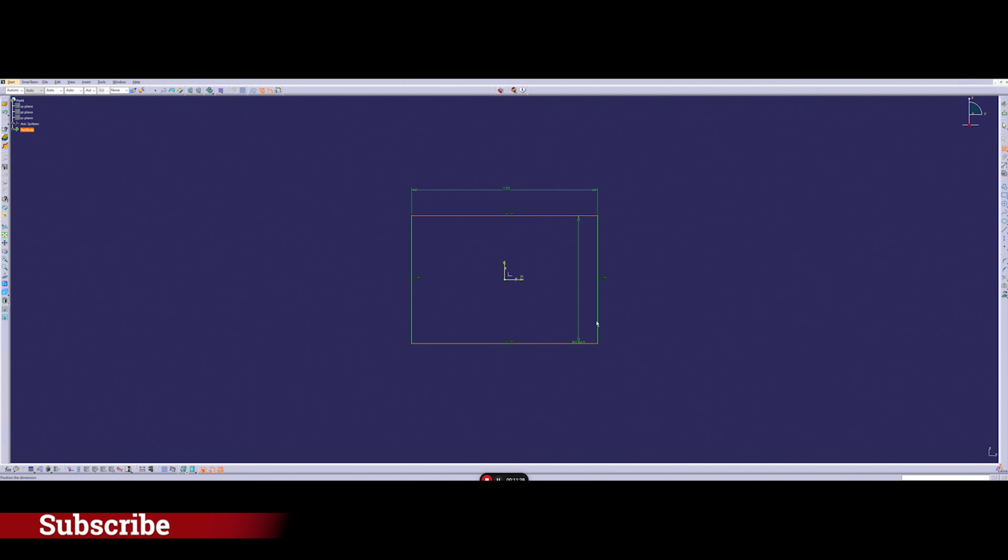So if I place the dimension that I want, which for example I can change to 75, or I can go even to 50, which is better, and here I can go to 100, then you see here that all my lines became green. It means that whatever I do here, I cannot move anything around. Okay, this is the first way to do the design.